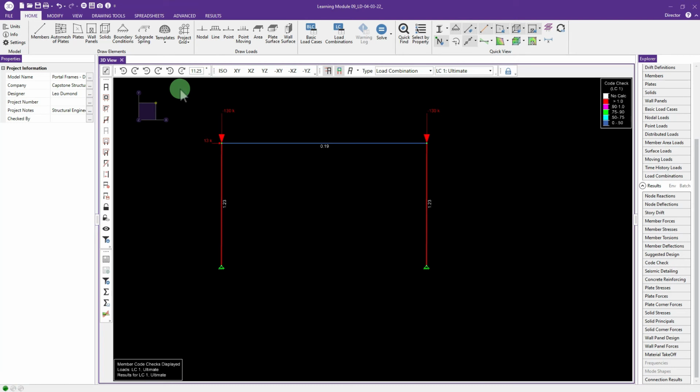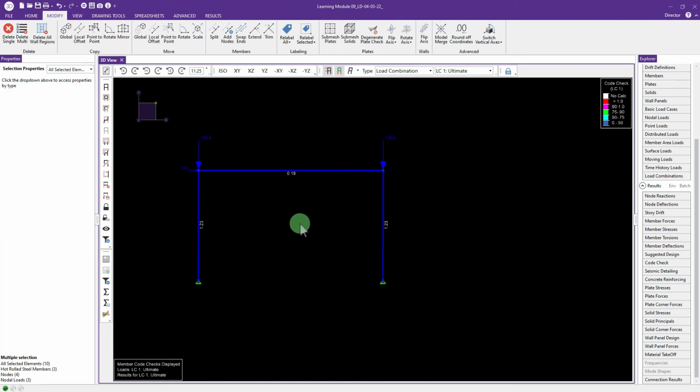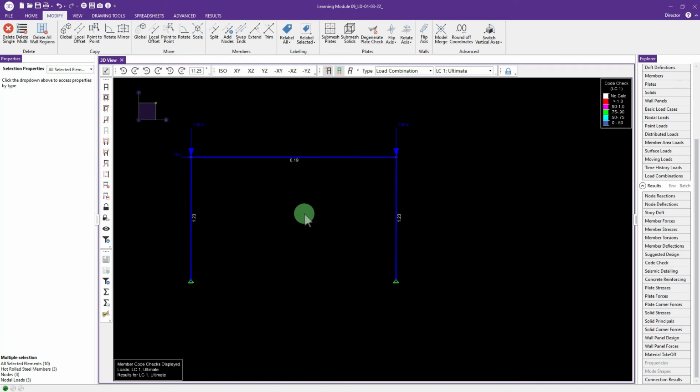When I say what we always do, this is for education purposes, so I'm demonstrating what I would normally do as far as showing differences in the analysis. But for actual design work, I would use a minimum of elements that have one node in the middle whenever I'm dealing with structural steel, concrete, or any one of these things, because you get a more accurate analysis.